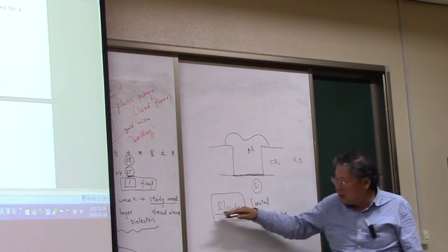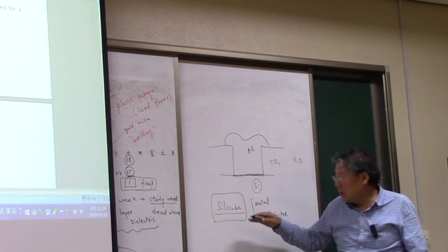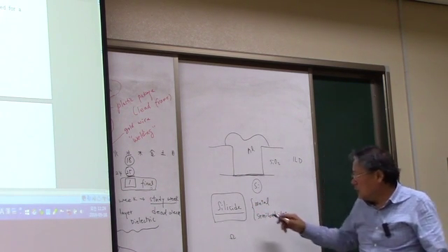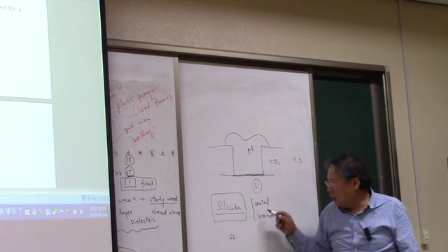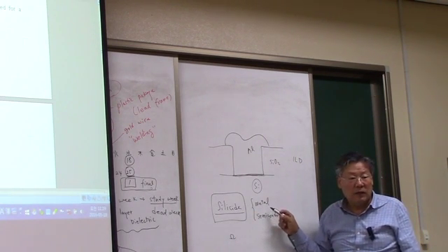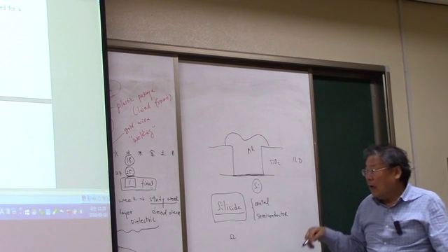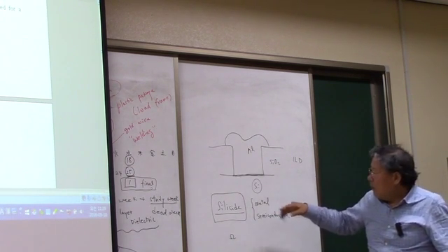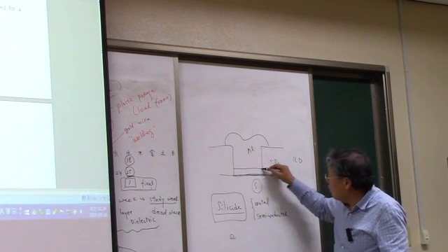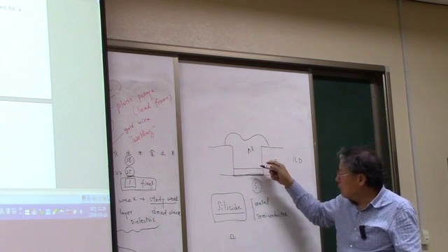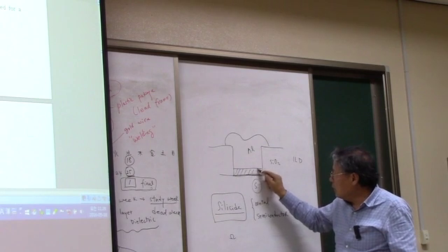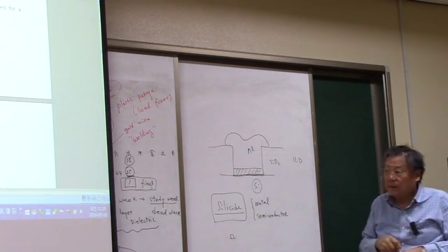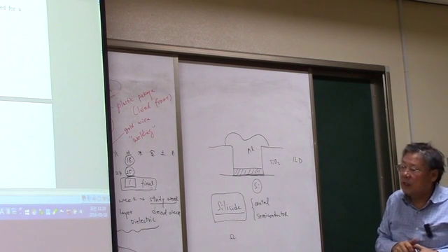So it's an intermediate materials. Okay, in terms of the resistivity, the silicide resistivity has to be in between these two, and thermal expansion coefficients and everything. So if you form a silicide before you put the aluminum metal on top, then the adhesion can be improved. Okay, that's why we form a silicide.